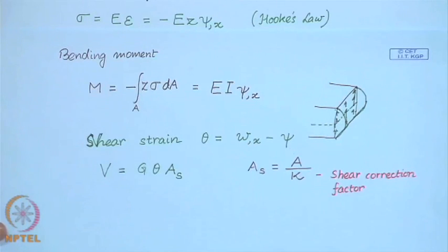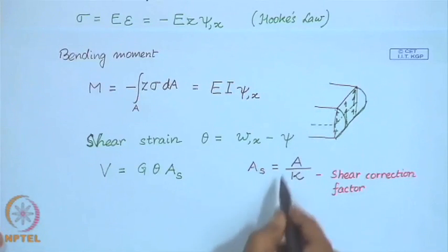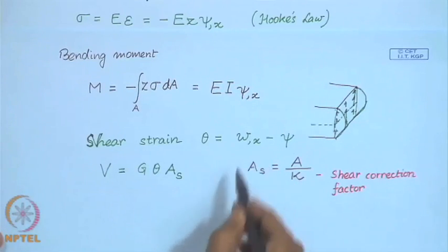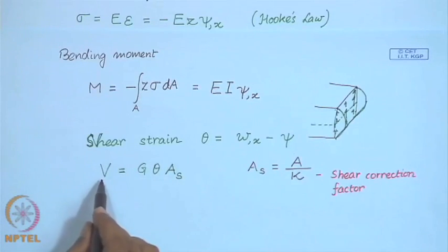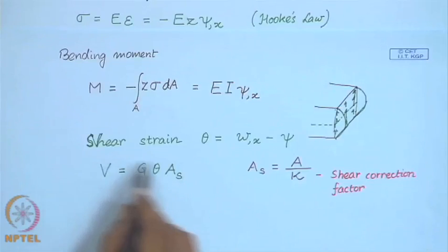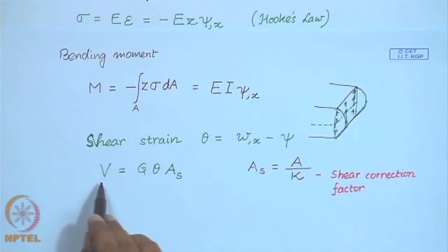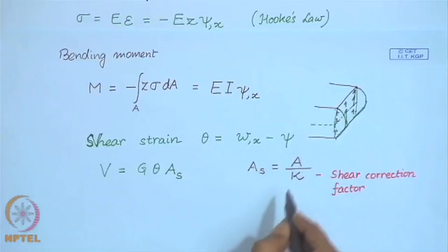Now, to take care of this fact, we introduce the shear correction factor and calculate a reduced area and multiply this area with the shear stress to determine shear force. So, we want to keep the expression of this shear force simple. For that reason we have introduced this shear correction factor.